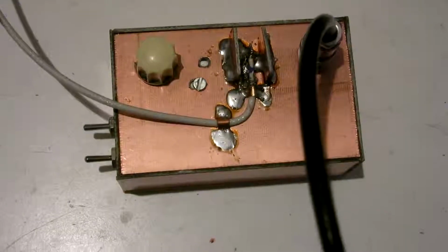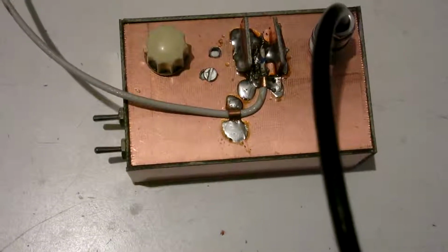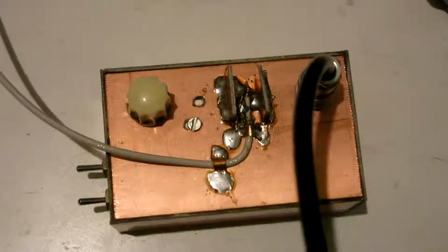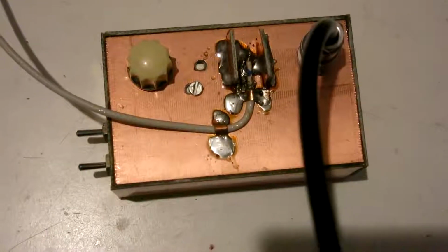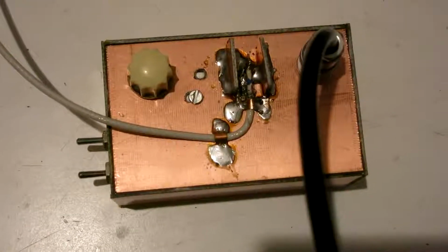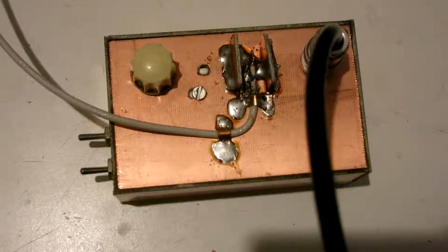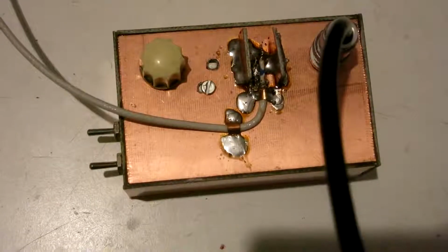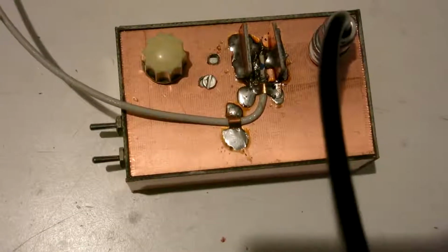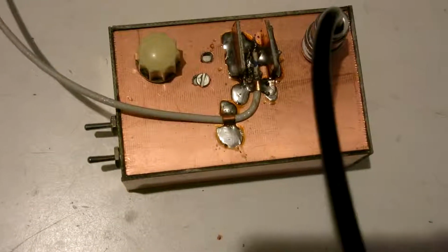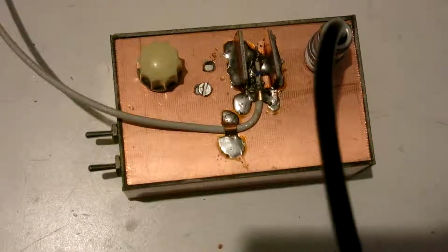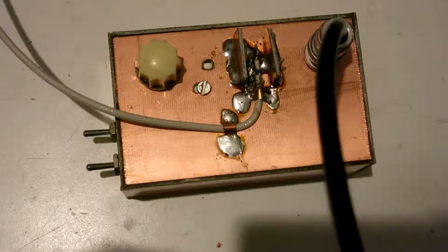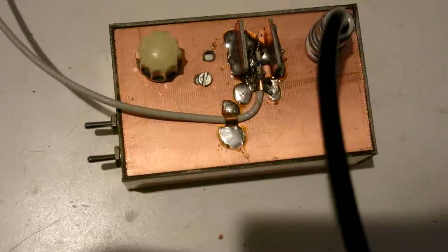Now I have replaced the signal generator with the pulse generator. This thing contains a 555, which frequency can be set by the knob and the two switches. It's followed by a divide by 2 IC, 74 AC 74, and then a 6 inverter IC. That's a 74 ACT 04 with all 6 gates connected in parallel. An RC link at the output makes a high-pass filter, so the pulses have a length of about 10 nanoseconds and an amplitude of about 5 volts.